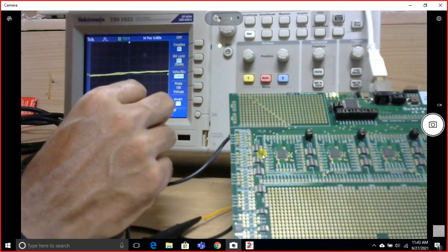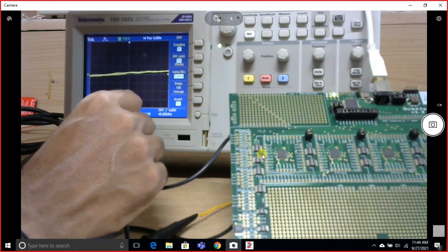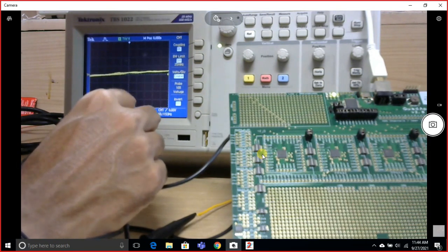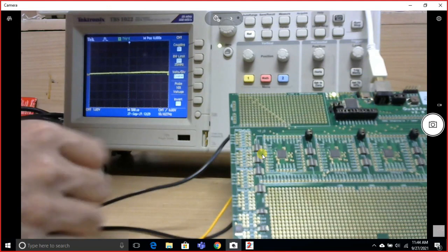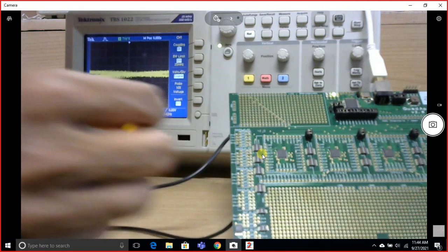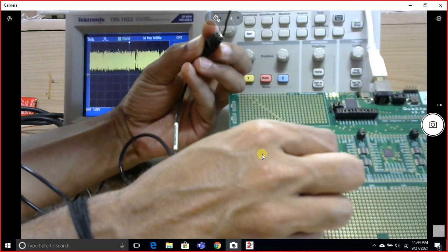Now you forgot everything. Simply connect O3P to the oscilloscope probe positive pin and O3N to the oscilloscope ground pin, the negative pin. Let us check the output first. We will proceed further, and later we will clarify doubts. Positive, direct connection.